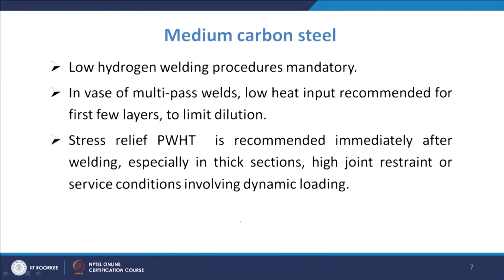Then stress relief post weld heat treatment is highly recommended immediately after welding, especially in thick sections. You also require it in the case of high joint restraint, or wherever the service is expected to involve dynamic loading.